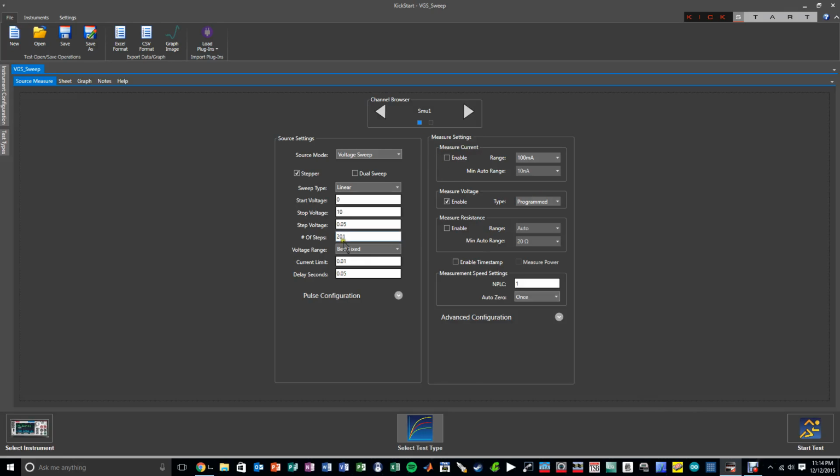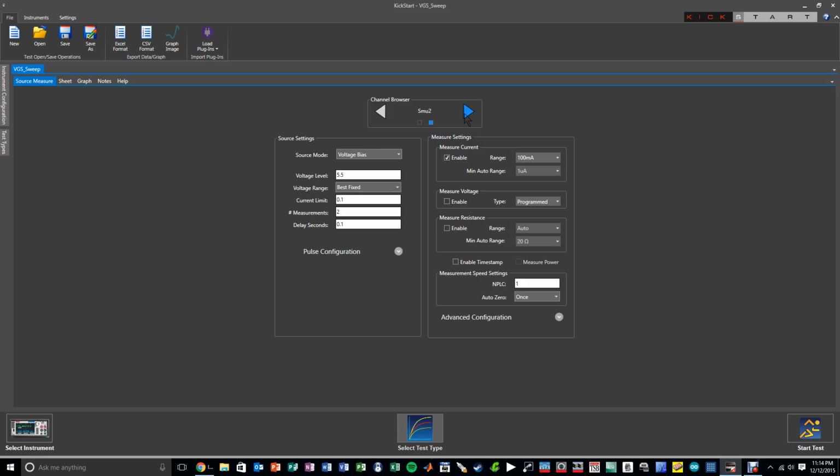This time we have to sweep the VGS of the device in a much finer step so we can extract that parameter with more accuracy. Here you can see that I'm sweeping the VGS from 0 to 10 volts at a 50 millivolt step, which is pretty nice. On the drain voltage, I'm keeping it constant at 5.5 volts. Now this is for the PMOS device, and that's why the drain voltage is 5.5, based on what we showed about the operating point we would like it to be.